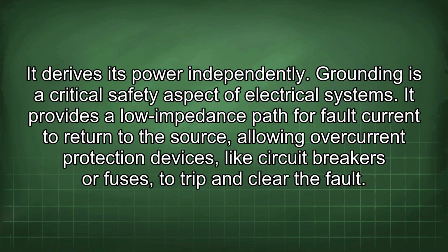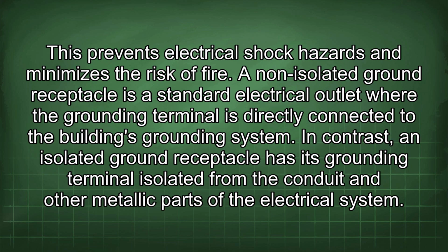Grounding is a critical safety aspect of electrical systems. It provides a low impedance path for fault current to return to the source, allowing overcurrent protection devices, like circuit breakers or fuses, to trip and clear the fault. This prevents electrical shock hazards and minimizes the risk of fire.